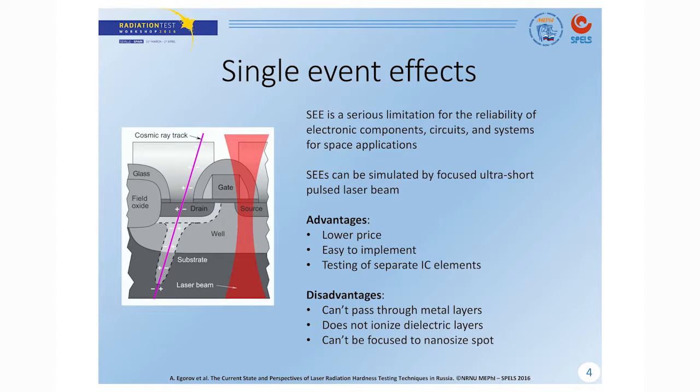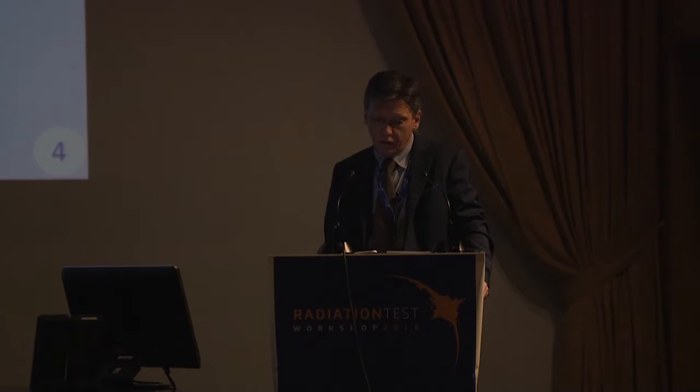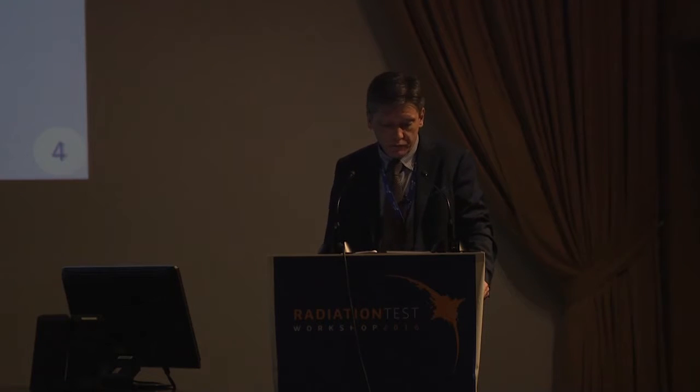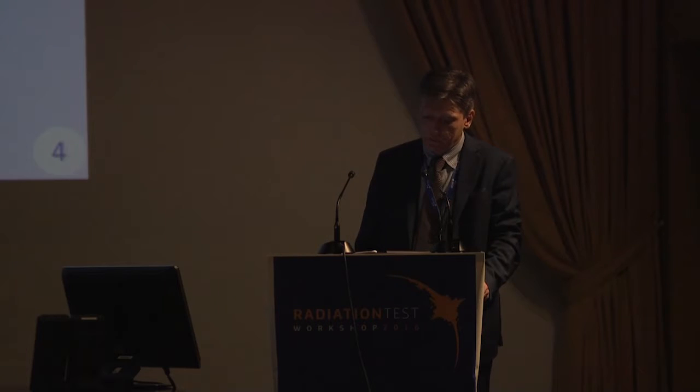As you know, single event effects induced by heavy ions, protons and neutrons have become a serious limitation for the reliability of electronic components. Single event transients in the IC can be simulated by focused laser radiation.